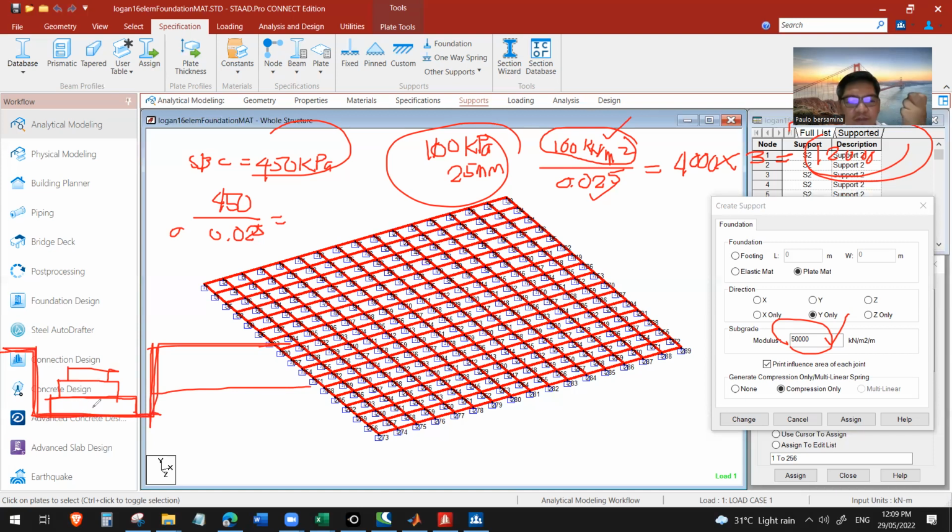So in the plate load test, if you read the ASTM standards, you should have plates, steel plates. They are heavy, so you can't let them fall on you. Then you have a load here, and we have a dial gauge here to measure the displacement. The load is applied incrementally.